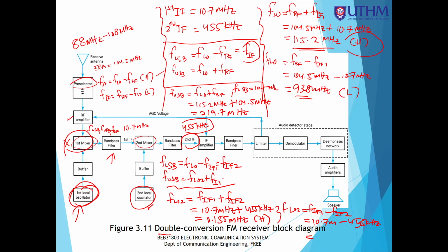It becomes 10.245 megahertz. This is if I use a low side injection. That means the local oscillator frequency is lower than the input.